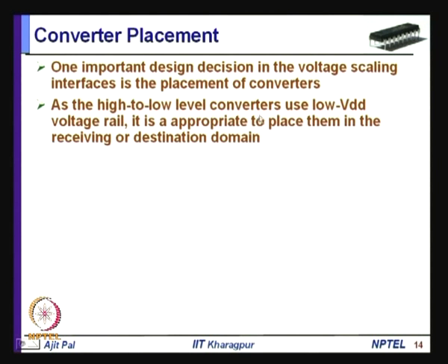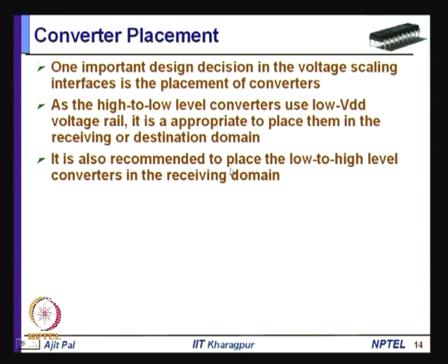As the high voltage level converter uses low VDD, I have already discussed that. So, it is also recommended to place the low to high level converters in the receiving domain. That was the previous case. In this case also it has been found that it is beneficial to put them in the destination domain or receiving domain.